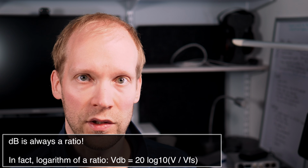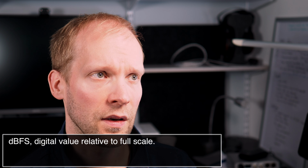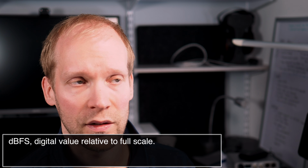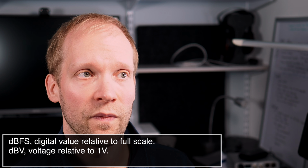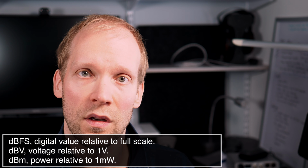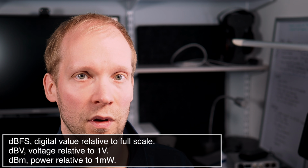And that's one of the main things of dB. dB is always a ratio. It is something compared to another reference signal. When we talk about THD in future videos, that's what's the distortion level compared to the fundamental signal. dBFS here is a digital unit, the signal level compared to the full-scale reference. Then we have dBV, which is the signal level compared to 1 volt signal. dBm, which is a unit of power, commonly used in RF engineering. That's the signal level reference to 1 milliwatt of power.